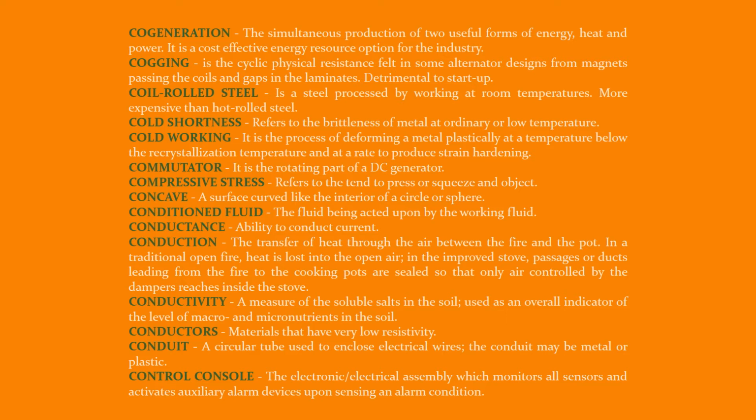Cogging, the cyclic physical resistance felt in some alternator designs from magnets passing the coils and gaps in the laminates. Detrimental to startup. Cold-rolled steel, a steel processed by working at room temperatures. More expensive than hot-rolled steel. Cold shortness refers to the brittleness of metal at ordinary or low temperature. Cold working, the process of deforming a metal plastically at a temperature below the recrystallization temperature and at a rate to produce strain hardening.